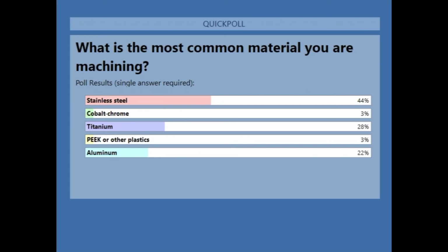We talked about the aluminum. That's the biggest thing, getting rid of the chatter. Titanium is very similar to the stainless in that it likes very light radial width of cut. Probably more problematic than the stainless is the titanium, because if you generate too much heat, since it doesn't shed most of the heat away in the chip, you'll go downhill very quickly. It's more sensitive than stainless steel. And for aluminum, chatter is probably the biggest issue, so having that mirror edge can really help with that.